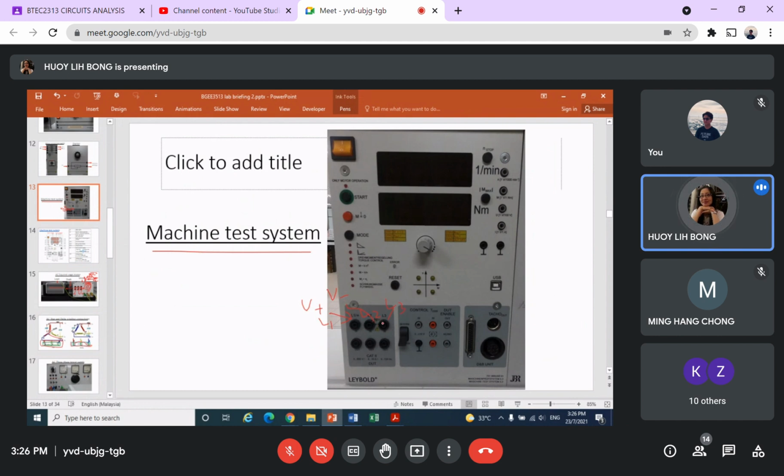For DC, the third one you can just leave open, you are not using it. For AC, we connect all of 1, 2, 3 to the top here. This is the input power or input terminal. The bottom is going out to the motor side, to the motor's winding.